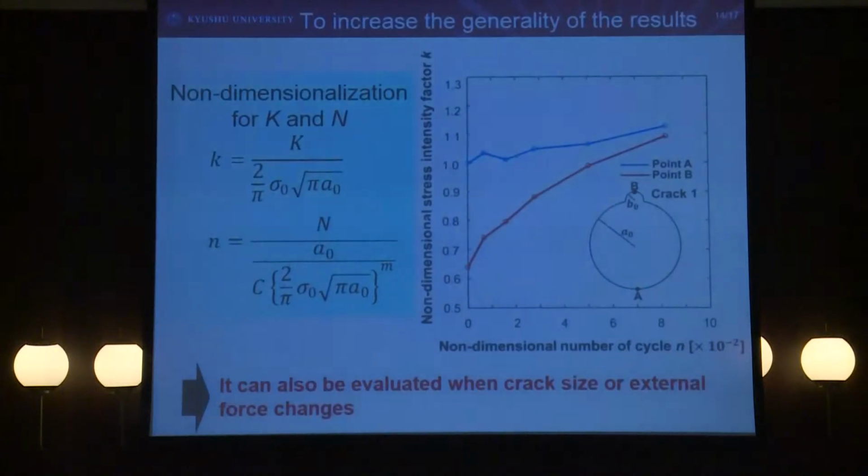And next, in this study, we analyzed a case study crack. So to increase the generality of the results, we propose these non-dimensionalization equations for stress intensity factor and number of cycles. Therefore, it can also be evaluated when crack size or external force changes.